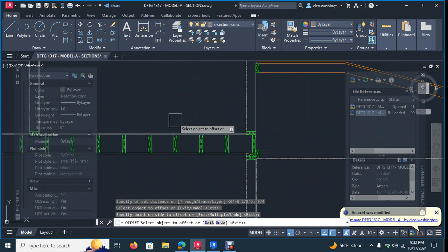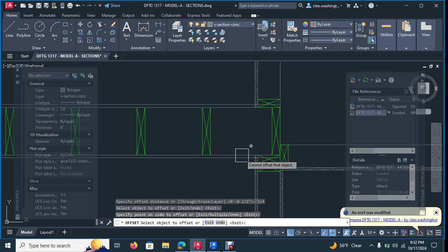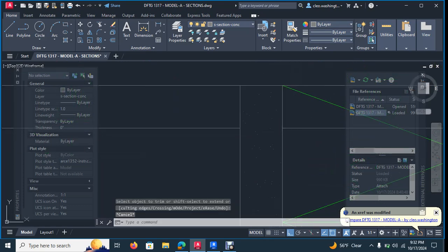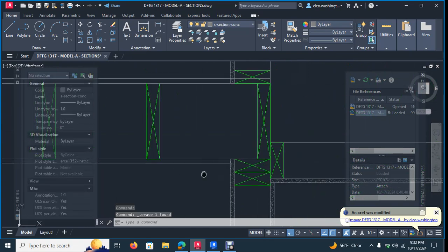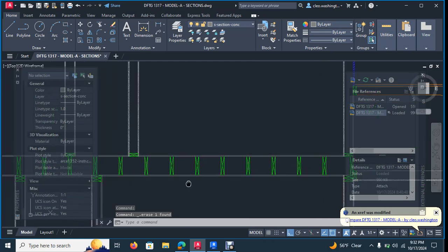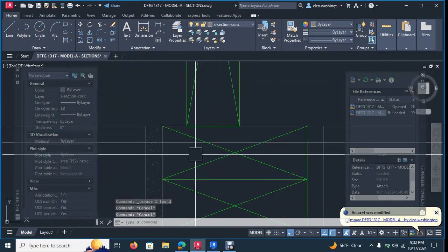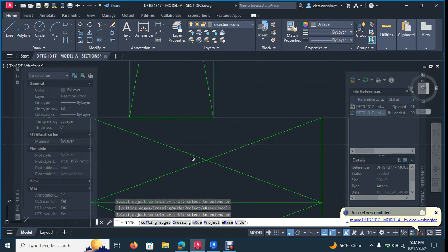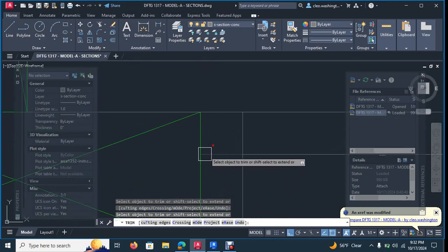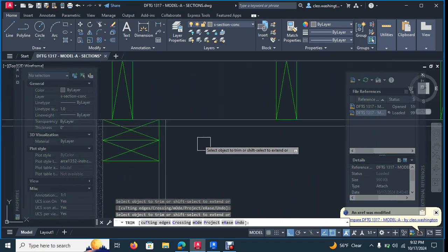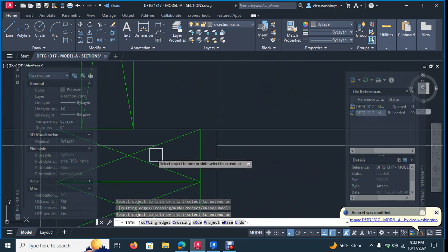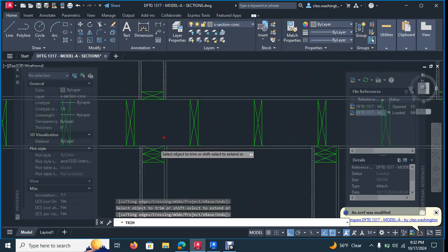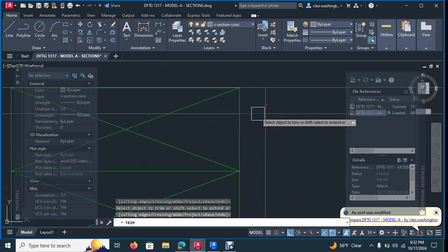And I know you guys don't know construction components, however, this is a crash course, so to speak. So let's go ahead and just clean it up here. Okay, the chipboard is going to stop at every wall. It's not going to go all the way through. So you type in TR. Trim it here, trim it here, trim it here, trim it here, and trim it there. And you'll continue that at all of these. Just go ahead and clean it up because the chipboard at the ceiling will not go through the walls.